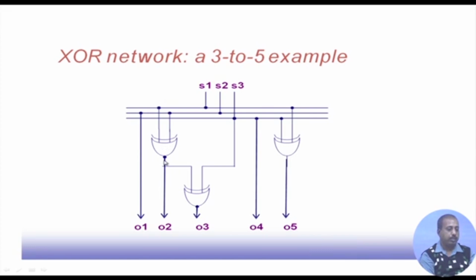This is done by means of the Gaussian elimination process to get a particular test pattern, what should be the seed value. That is obtained, and then that seed value is fed from the ATE, and this decompressor is calculating the pattern that will be fed to the circuit for testing.